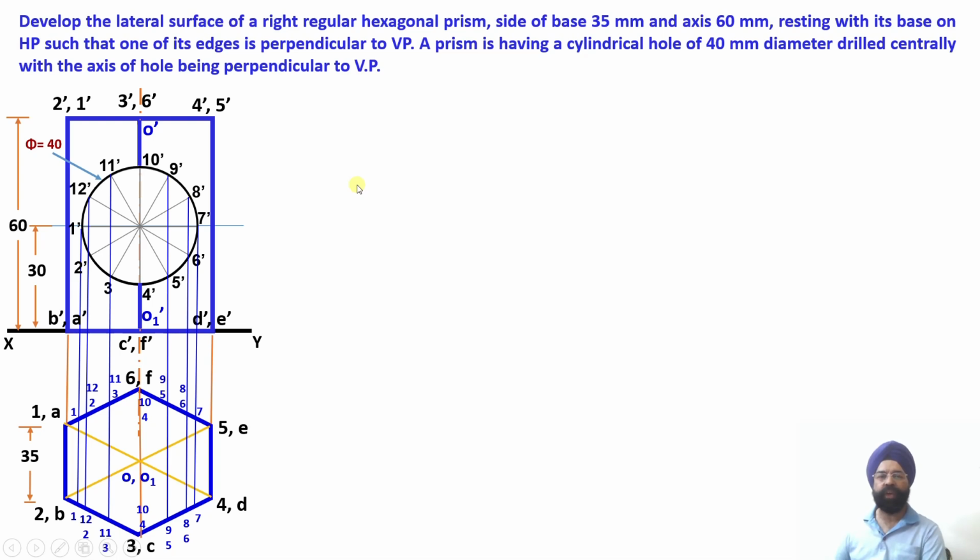So now let us start working out the development using the parallel line development method. Here you can see in this particular case we have got two things which we need to keep in mind in order to draw the development. Two things are required, that is true length. Please check, true length of the height and the width of the base edge will be required.